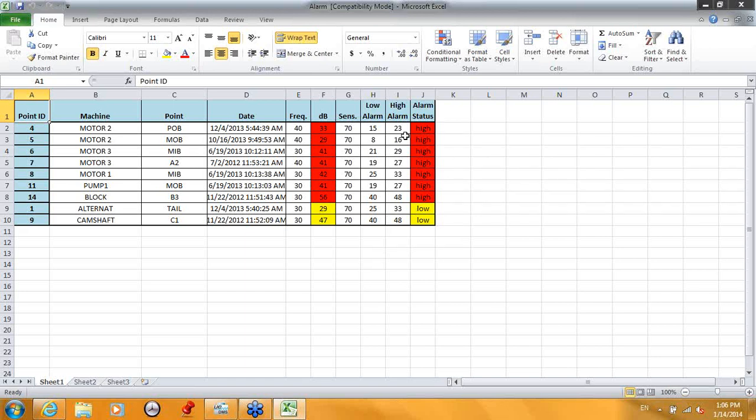Usually when it comes to bearings and you got a red flag, we have it set up 16 decibels above its original baseline reading. Basically anything that hits that mark gives us a glimpse telling us that we got starting stages of possible physical damage of that bearing. So if we pull that bearing apart and actually look at it with our own eyes, we can possibly see the flaking, the spalling, or even the flat spots on the bearing itself.